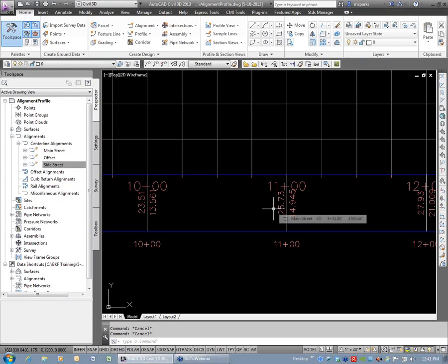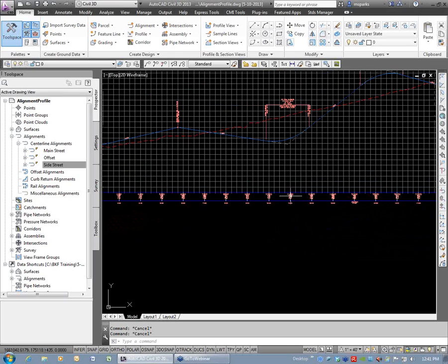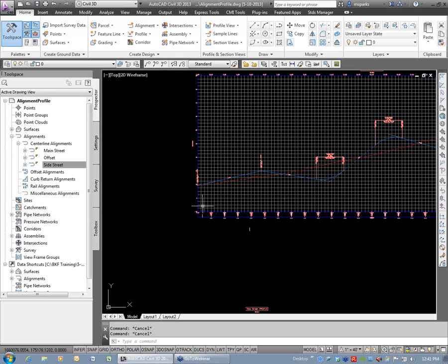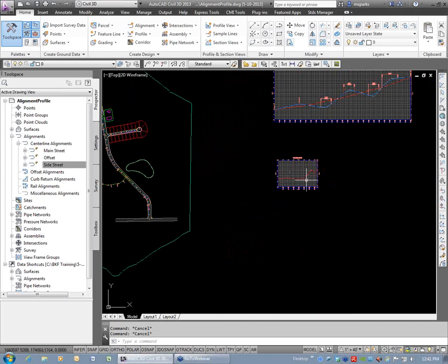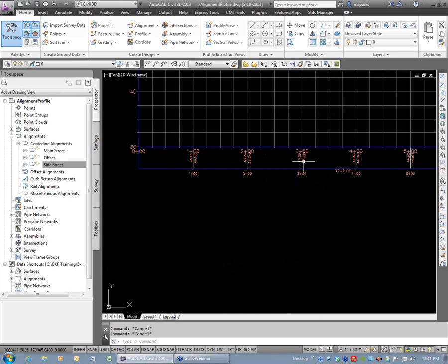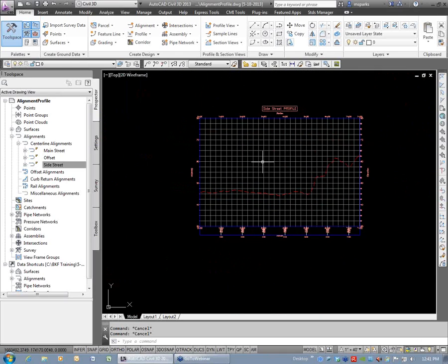If you're going to use these bands to plot, you want to make sure that they're obviously referencing the right elevation. And it's about styles as far as precision, things like that. So there's your 4 steps, right? This one, we've already created alignment, and the existing ground profile, we need to create a finished grade profile and then change those numbers as well.